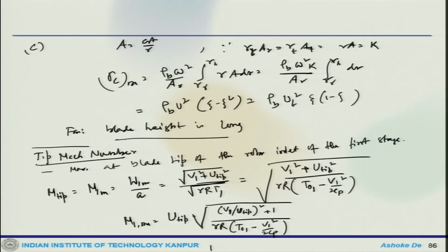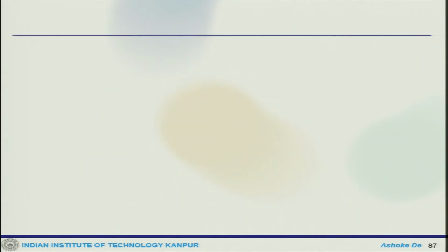Okay. So, from this particular equation, for a specified tip Mach number and rotational speed, the axial velocity at the inlet can be determined. Now, for a transonic compressor, an acceptable value of tip Mach number would be around 1.3, while for the fan in turbofan engines a much higher Mach number is expected and allowed, which would be typically 1.5 to 1.7. So, the challenging design is to increase the rotational speed U and keep the tip Mach number within the acceptable limits. This can be achieved by inlet guide vanes.